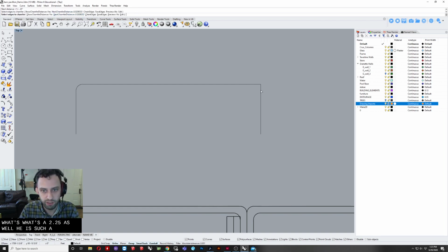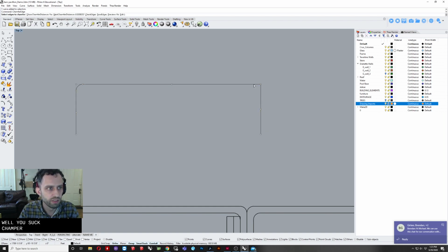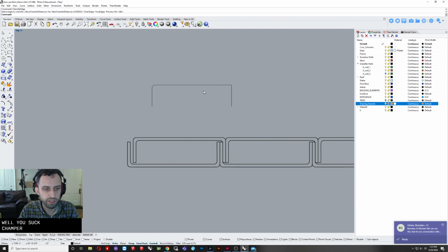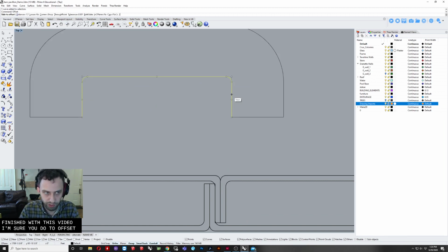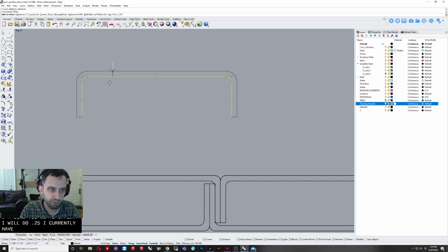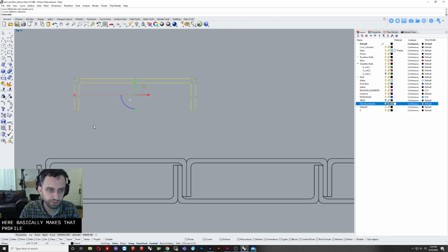If you do select chamfer, why isn't it chamfering? Oh, okay, I'll try that again some other time. I just want to be finished with this video, as I'm sure you do too. Offset, we'll do 0.25. I currently have cap turned on. So you can see here, basically it makes that profile.